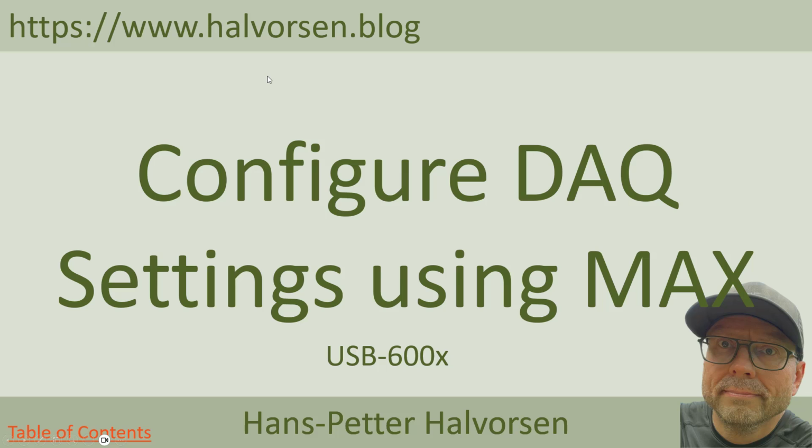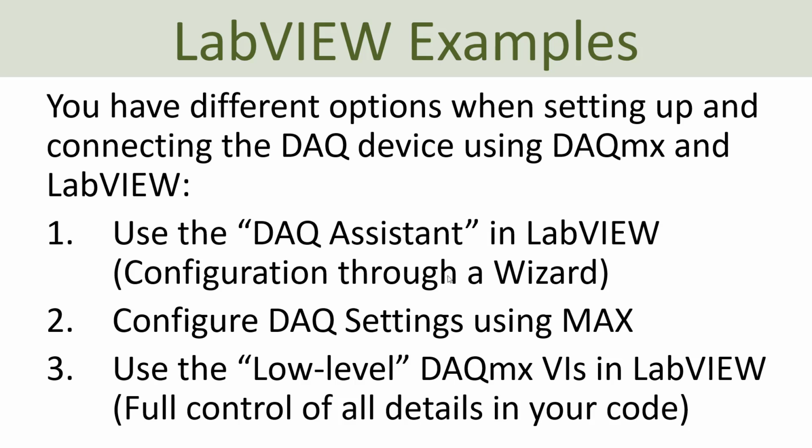So now we will use an alternative solution. Now we will configure the DAQ settings using the Measurement and Automation Explorer. So now we have learned how to communicate with a DAQ device from LabVIEW, and we first needed to install this DAQmx driver software in addition to the LabVIEW software, of course, and then we use this DAQ assistant, which was an express VI that we could use inside LabVIEW in order to communicate and read values from our DAQ device.